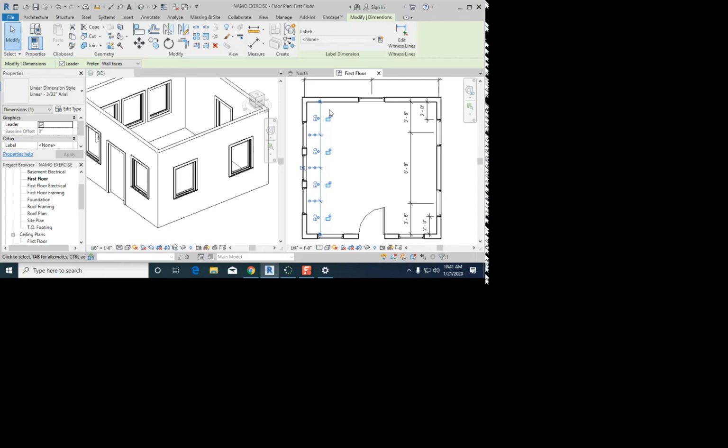Ashley, did you have a question? I did these dimensions, but let's do the 2 feet too. So I click on the outside? No, inside face, just like mine, and then right here. Now basically where we want to take it. Okay, and now hit escape just to get out of dimension. You might have to hit it a couple times.